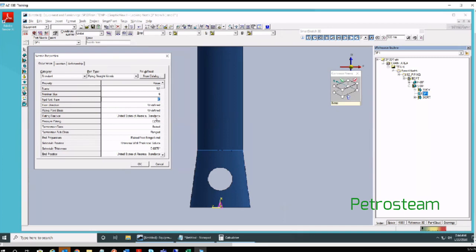The remaining things are the end preparation. The rating for the nozzle is class 150, its type is bolted, and its end preparation is RFFE, raised face flanged end. The end practice and rating practice are the United States of America standard.